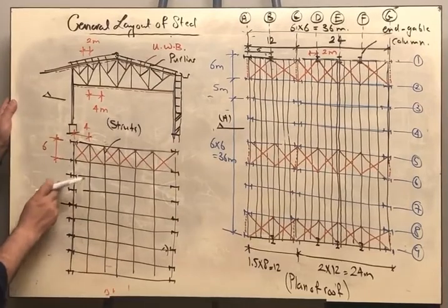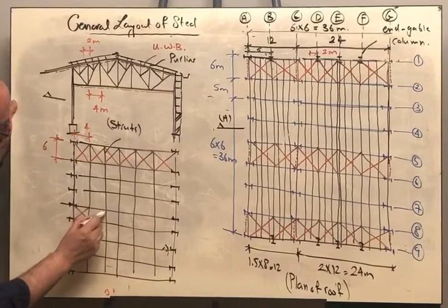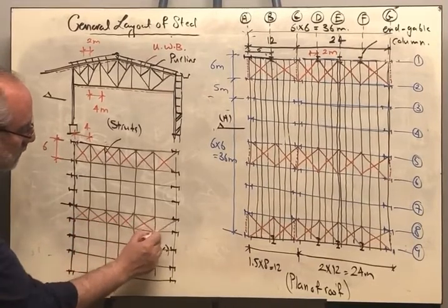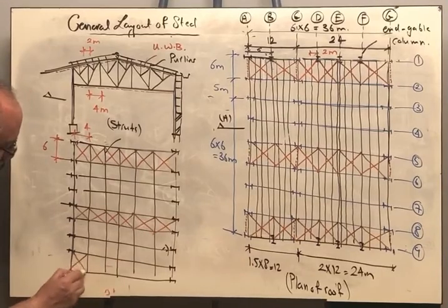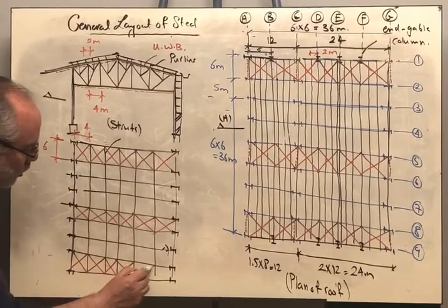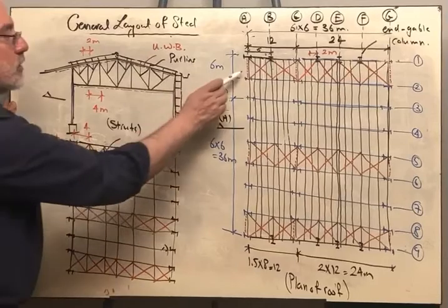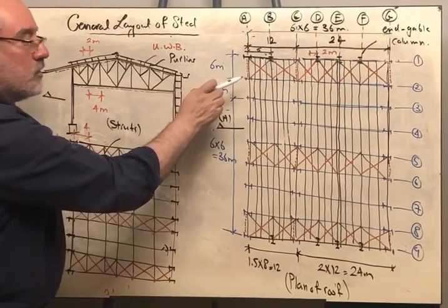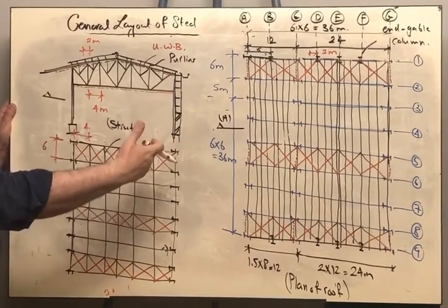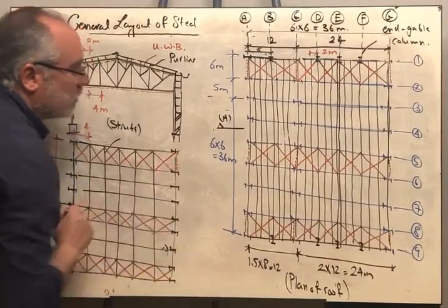So also here I will have lower bracing, and here I will have also lower bracing. Whenever we are having lower or upper bracing, there should be an indication for the vertical bracing. We should show the instructor that we understand whenever we are having horizontal bracing, it will transfer the force to a vertical bracing, and this is the indication of the vertical bracing.